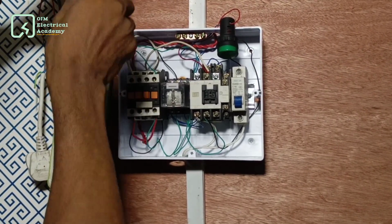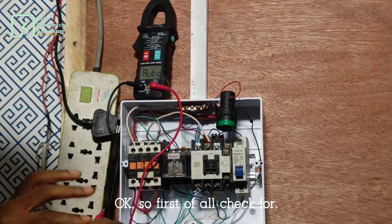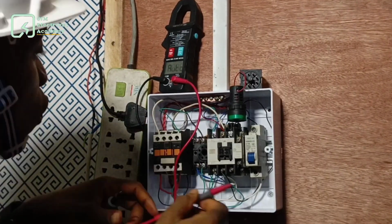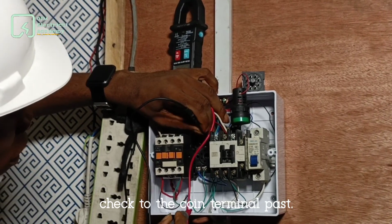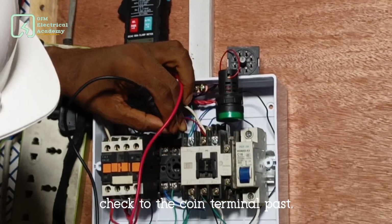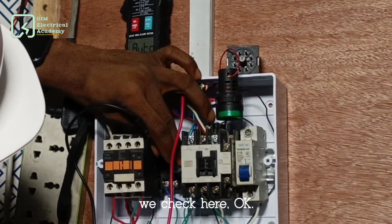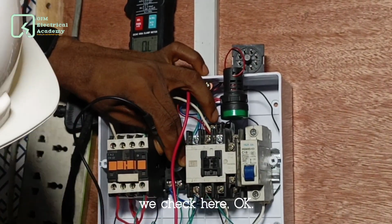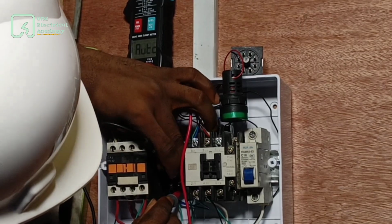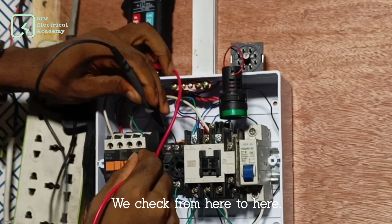So let's check. First of all, let's remove our relay first. There is a lot we need to check from here. First of all, we check the coil terminal, passed. So we check from here to here, we check from here to here.